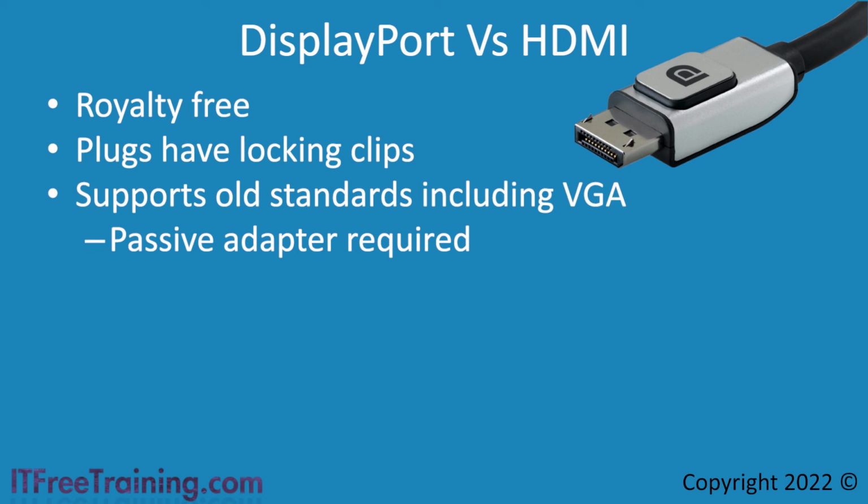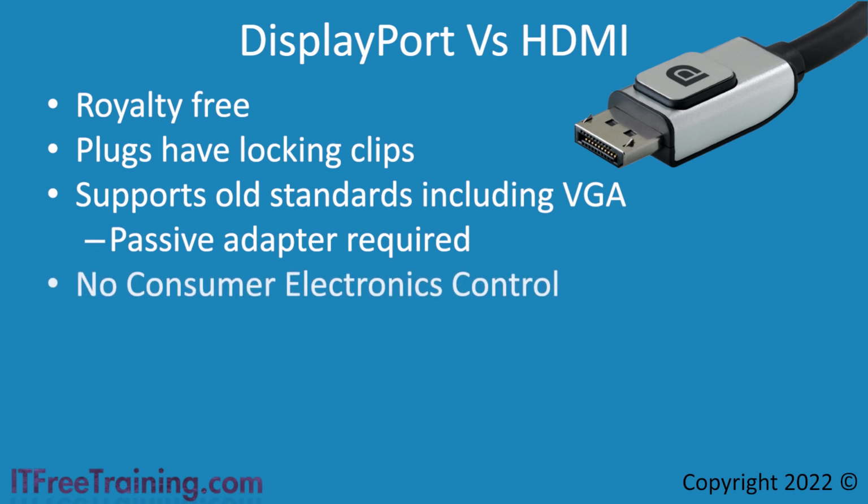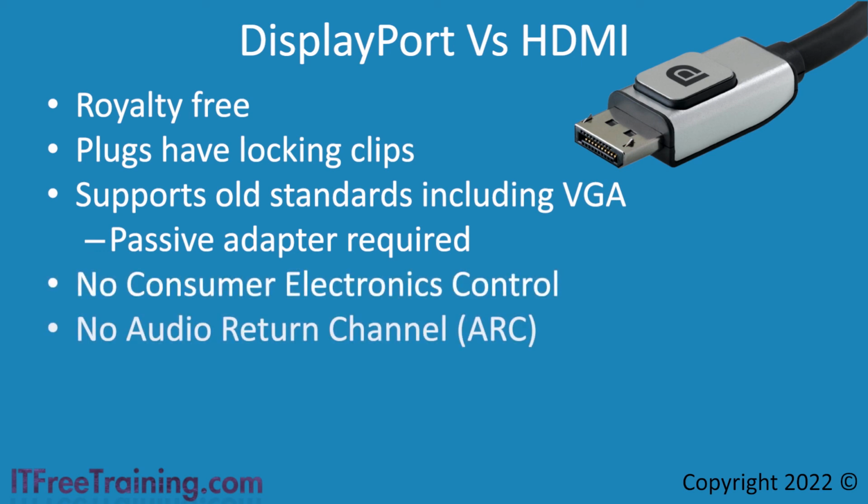Given how old VGA is, I don't think this will generally be a problem, but the feature is there if you should need it. HDMI was designed primarily looking at home devices, while DisplayPort was designed primarily for computing devices. For this reason, it does not support features like consumer electronics control and audio return channel. These features are good features to have for a home system, but for computers are not really needed. DisplayPort, however, does have an auxiliary channel which allows data to be transferred in the reverse direction, as ARC does.